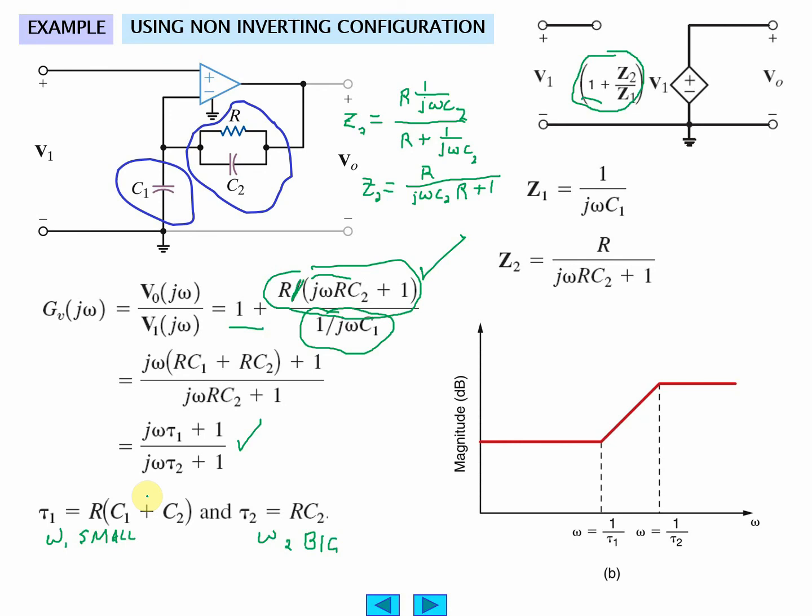So what we're going to have is a Bode plot that looks like this. We don't have a negative 20 dB starting out because we don't have an omega times something. So zeros make it rise. Omega 1 is smaller, so here we go, 1 over tau 1. We're going to have a rise right here. So it's going to be flat line, rise, flat line.